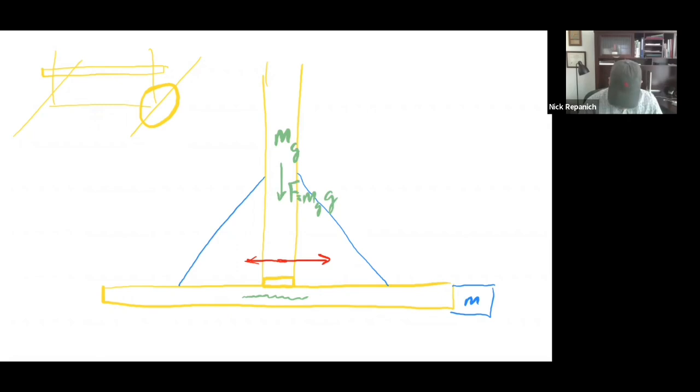When you look at this bearing, when it's just sitting there static, there's not a moment, it's just a plain force, and the force is in that direction. So in this case, you would go grab your mechanics, and it would look like this. Here's the motor end, where the motor attaches. Here's the carriage. The gantry might be sitting right here, and so it puts a direct force right down on it. Statically, it's just got to carry the load. Can the bearing handle that?